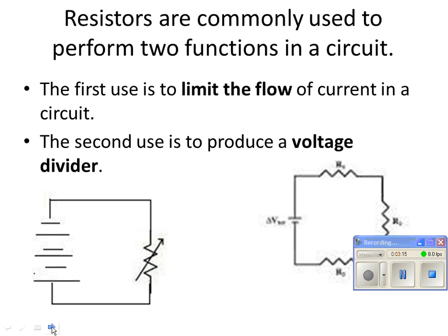So let's turn it up now. Let's just try a different spot. Let's turn it up to 12 ohms of resistance. How much current is flowing at 12 ohms of resistance? 1 amp. So just from going from 1 to 12 ohms, we went from flowing 12 amps down to 1 amp. You see what's happening? If you hold the voltage steady and you turn the resistance up, the current goes down.